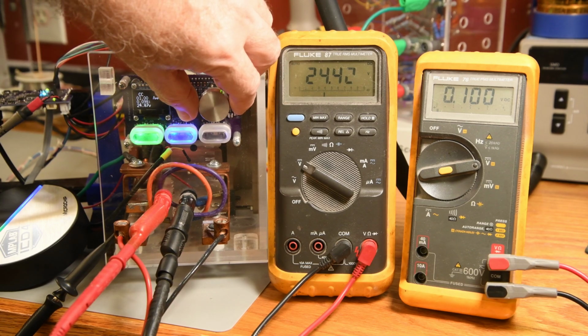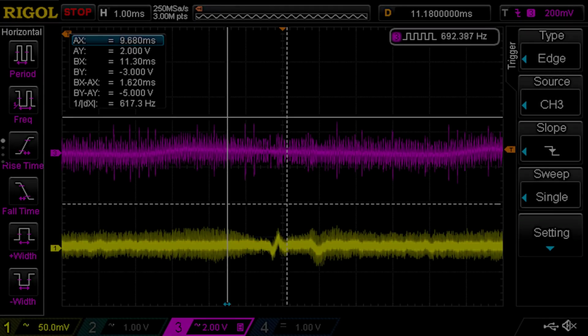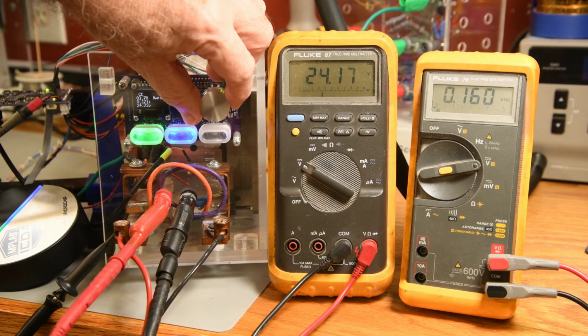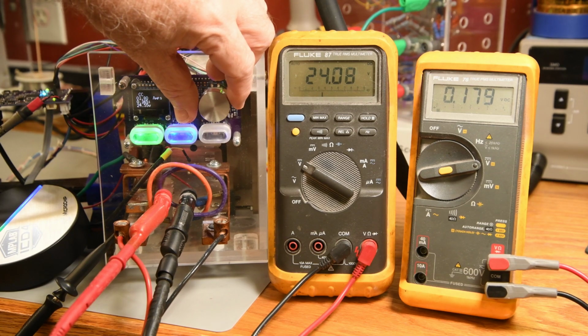Now this is the start of a problem. This is a great waveform here. It shows 2 problems. One I have a plan for fixing. The other I have a sinking suspicion the root cause is from the MOSFET power modules. In the center of the yellow drive waveform is a nice little ramp. That is coming from the interaction between the fans and the power supply. I have already decided to redo the power supply, so that one I'm not going to worry about. The noise in the voltage and drive signal is a big problem. I do like the fact that the set value is close to what the load is pulling.